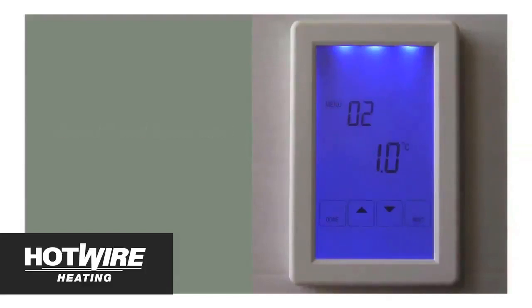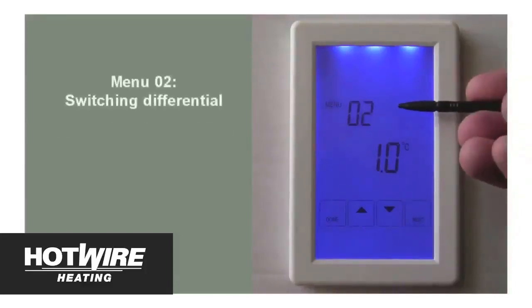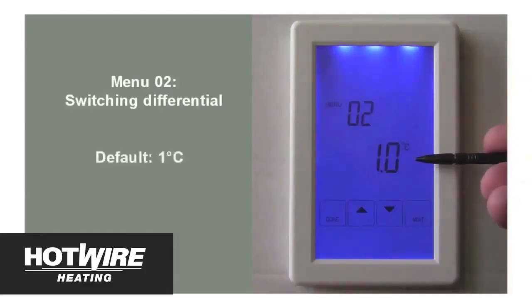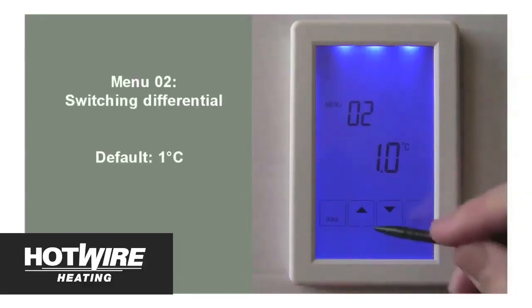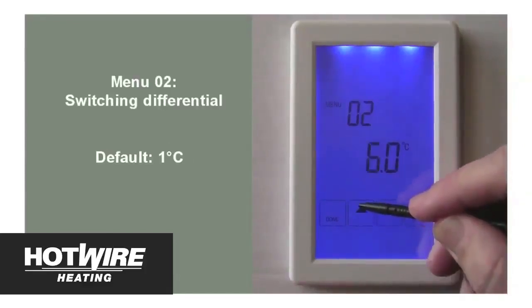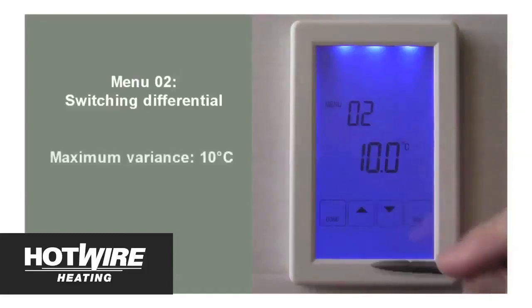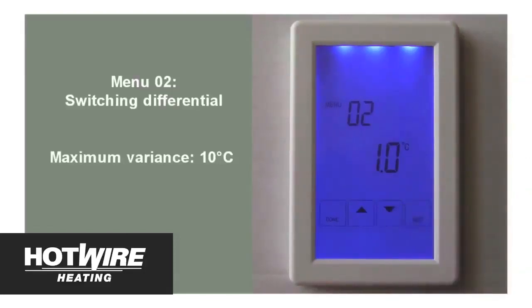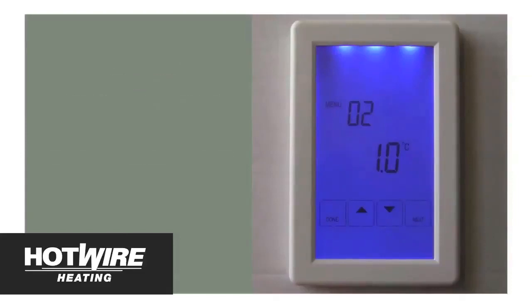Menu 2 is the unit's switching variance, which is set by default at 1 degree. This determines how often you want your unit switching on and off when maintaining the floor temperature. When set at 1 degree, it means the elements will switch on when the floor temperature falls half a degree below the desired temperature and turn off when it gets half a degree over your desired temperature. You can increase this variance in temperature up to 10 degrees. In this case, however, we will leave it at the default temperature variance of 1 degree. Press Next to move to the next menu.